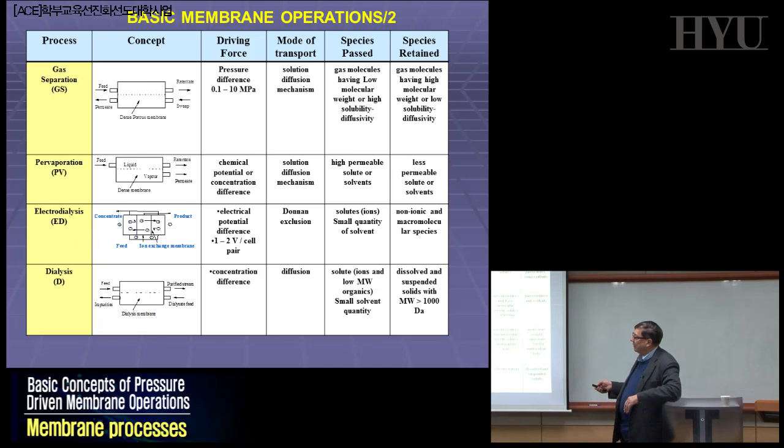Whether your membrane is PVDF, polypropylene, or polyacrylonitrile, etc., is relatively important, because the whole mechanism of transfer is just size exclusion and convection. So it depends on the size and the morphology of the system, and in first approximation does not depend on the chemistry of the system.